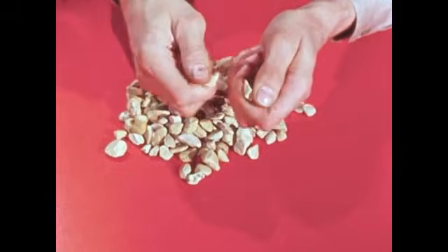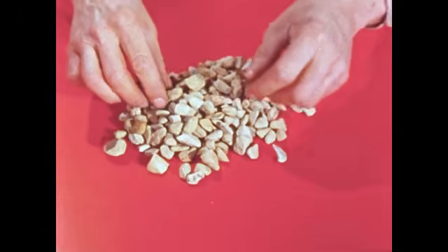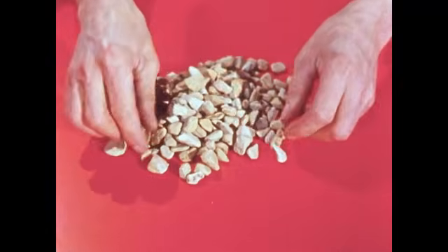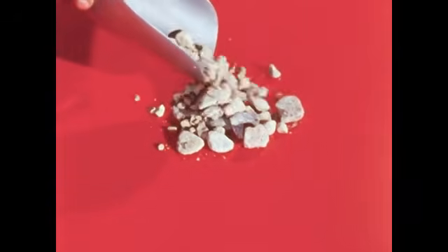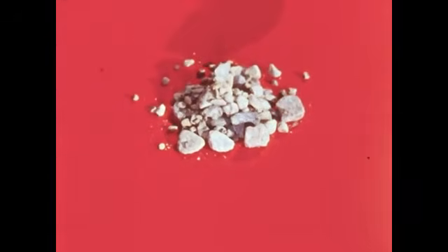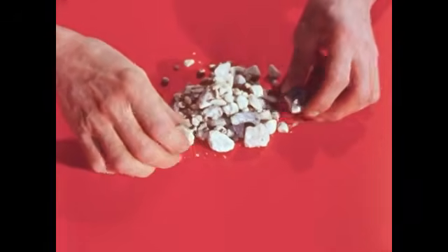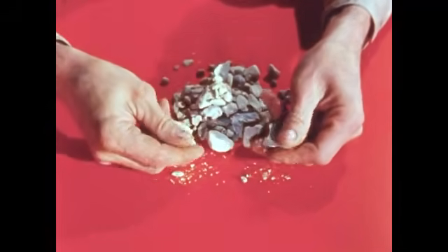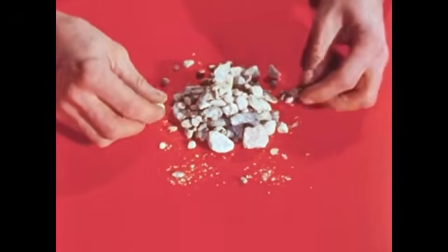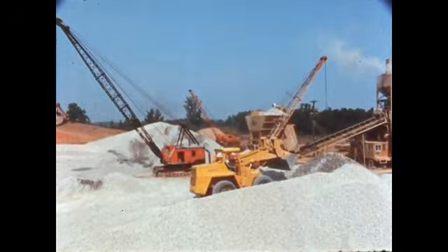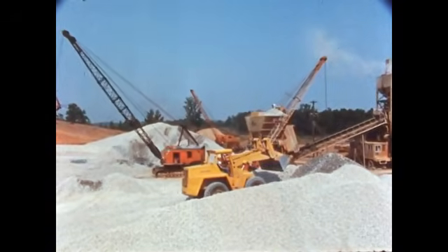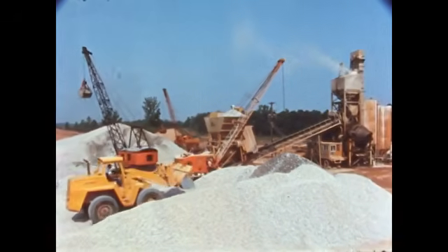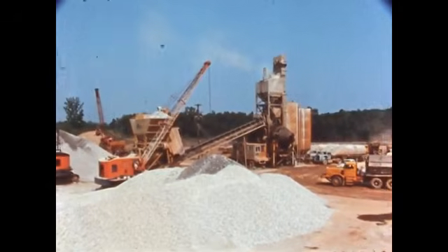Brittle stones are weak and produce concrete of low strength and durability. Soft particles absorb water when wet and lead to pop-outs when frozen. Dirty aggregate coated with clay or organic material that will seriously impair bonding with the cement paste should be rejected or used only after thorough washing. Fine and coarse aggregate within a specified range of gradation sizes are used on construction jobs.